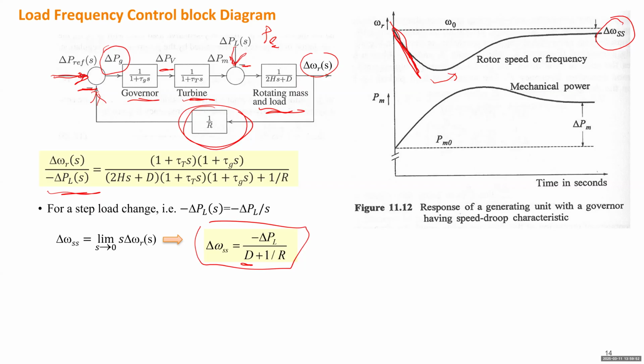The reason is the load frequency control by the governor is basically just a proportional controller. A proportional controller cannot eliminate the error of the control variable. You have to introduce some control which is similar to an integral controller. So does everybody know integral controller, proportional controller, and differential controller?